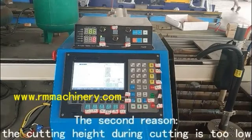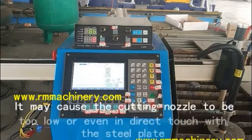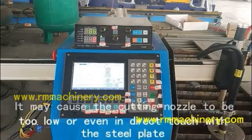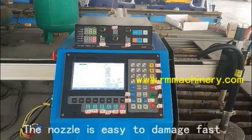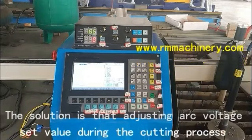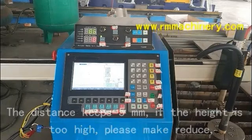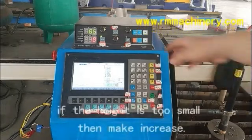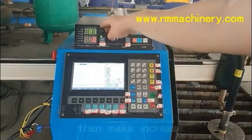The second reason is that the cutting height during cutting is too low. It may cause the cutting nozzle to be too low or even in direct touch with the steel plate. The nozzle is easy to damage. The solution is to adjust the arc voltage during the cutting process. The distance keeps 5 mm. If the height is too high, please reduce it, and if the height is too small, then increase it.